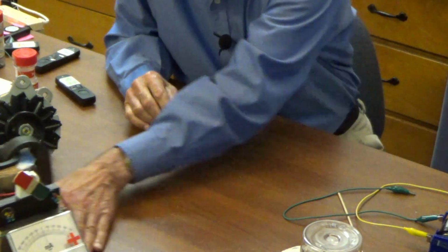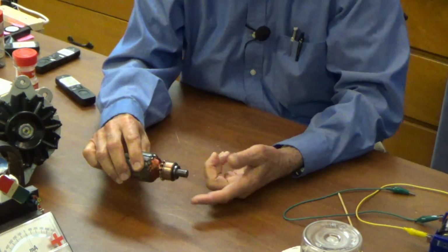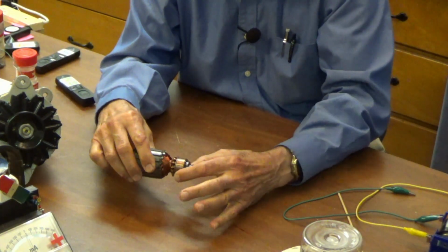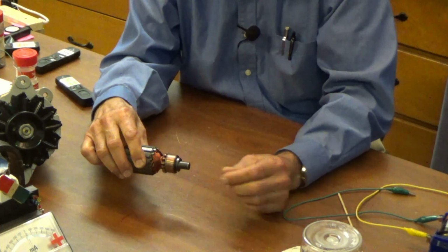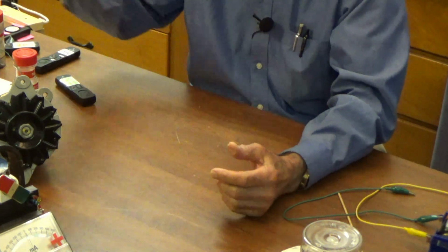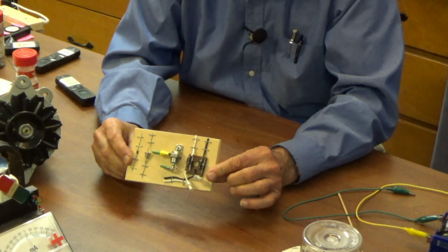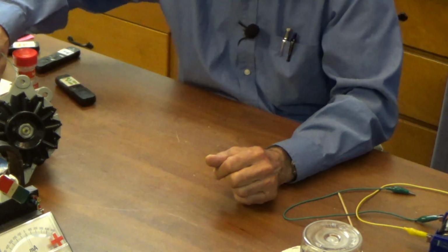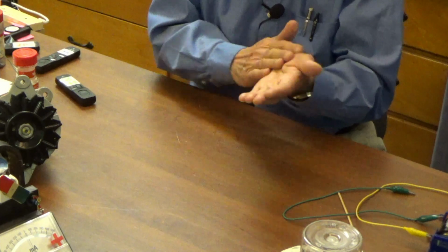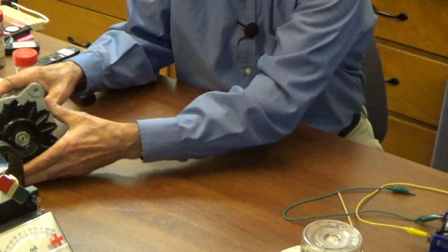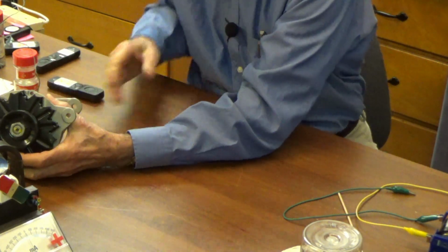We now have alternating current, and we didn't have to use a commutator and brushes, which are a maintenance problem for something that's running all the time. And we didn't have to use diodes. And like I said before, we can raise and lower the voltage using a transformer when we're working with alternating current.